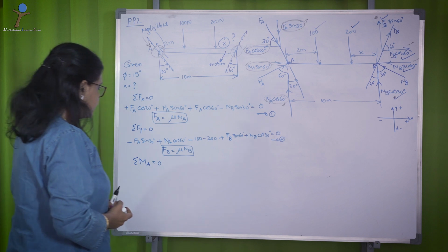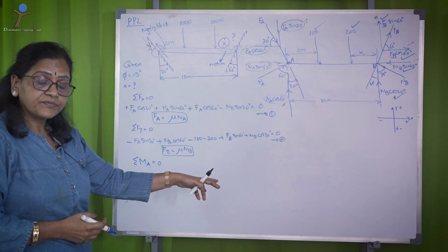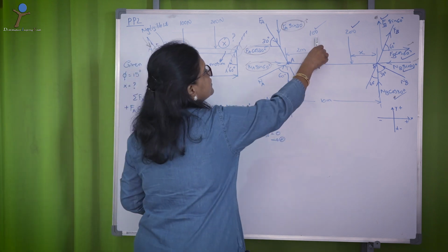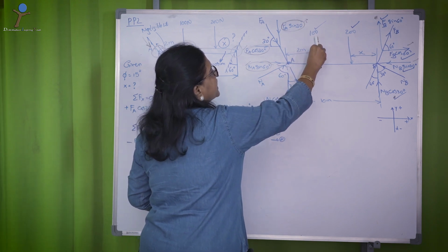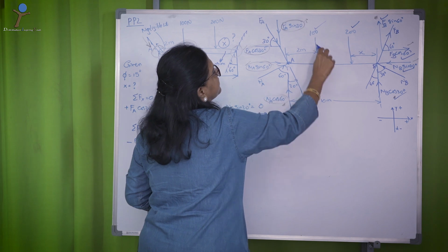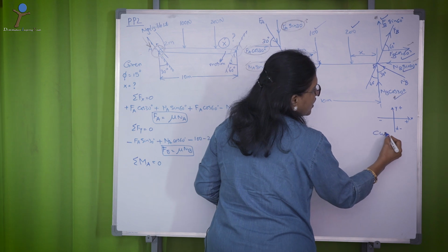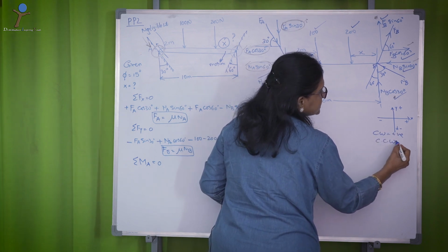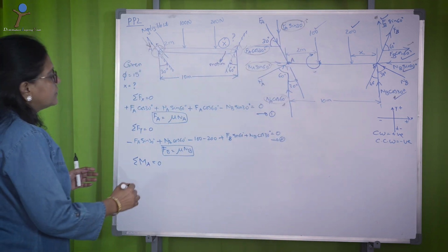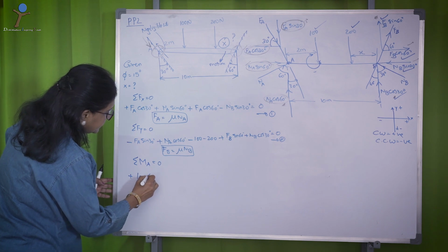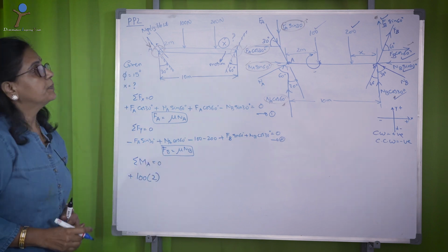So, step by step, let us put down those values of moment. As we said, moment is force into distance from the axis. Now, this is the force, this is the moment center. So, rotate the force which is in vertically downward direction towards the moment center this way. So, here in moment again, let me recall, clockwise is positive, counterclockwise is negative. So, here this is clockwise, I call it positive, where force here is 100 multiplied by the distance here is 2, 100 into 2.